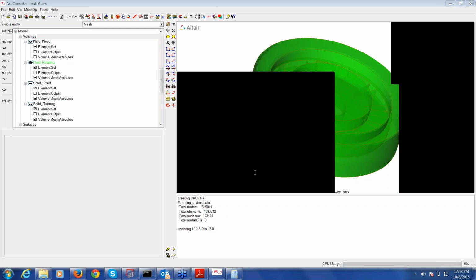Okay, what is the purpose of using mesh zone refinement? Basically, when you do zone refinement, the mesh would be refined over that particular zone, whatever you create over the car. So there will be a finer mesh apart from your wind tunnel when you create that mesh zone refinement.